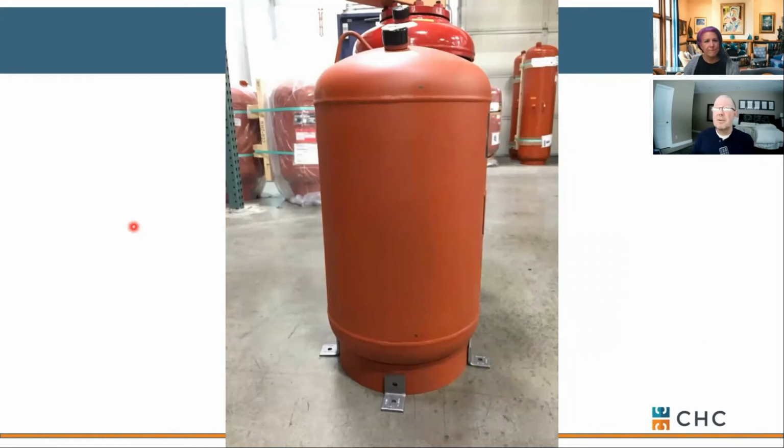Another thing to think about is how do you restrain a tank? Typically, you're adding some angle brackets to seismically anchor this down to a housekeeping pad so it doesn't tip over in a seismic event. Most of the time you can weld or drill to what we call a collar, the bottom of this tank here. What you can't do is strike an arc to the vessel itself, okay? An inspector considers this tank ASME, but the collar is an exception. So you can drill or you can weld to the collar, but you can't strike an arc to the vessel.